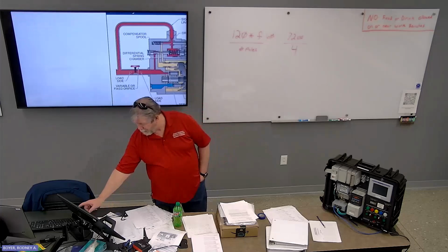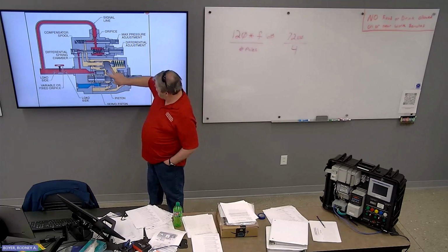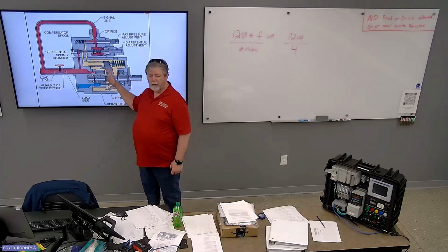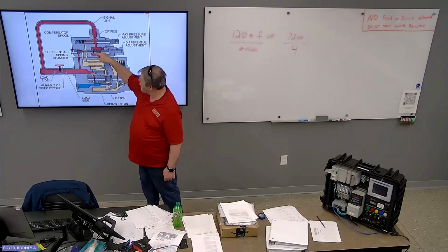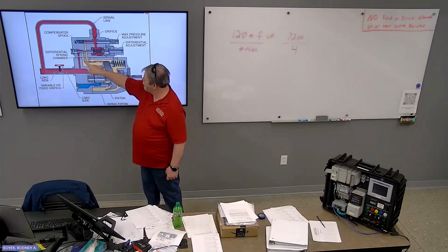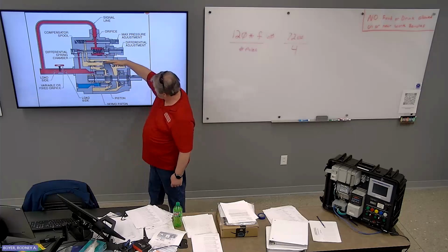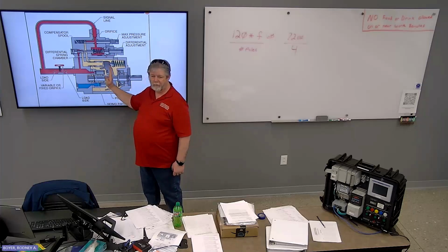There's pressure compensated. That's your main shaft, what's known as a wobble plate. And it changes its pitch based on what this feedback signal is doing. Provides fluid here. Of course, it's spring return, but it pushes, bringing it more vertical.